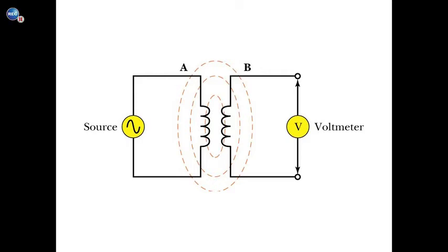I should also point out that this only works in an AC circuit. If this were a DC circuit, when the current flows in one direction, the magnetic field would grow, and then that's it. Right? The magnetic field then would be stationary until we turn the circuit off, and then the magnetic field might collapse. So with an AC circuit, we have the growing and collapsing magnetic field, and that is necessary for a transformer to operate.